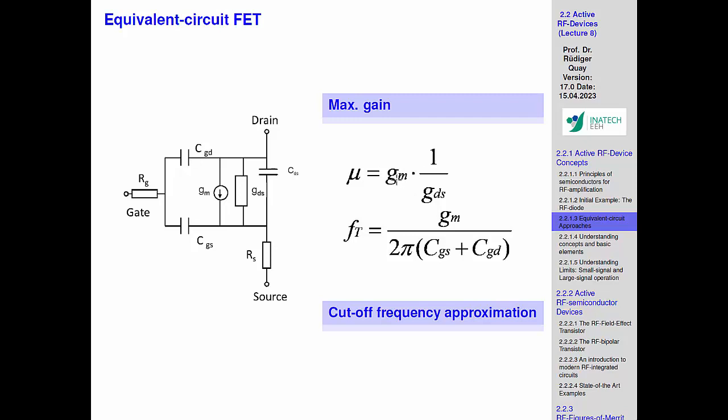there should be no current change based on the output voltage change. This output voltage change should be independent. Yeah? And the input should not be modified. These are the two constituents of amplification. That is very key. People tend to forget this only because otherwise it would just be resistive.